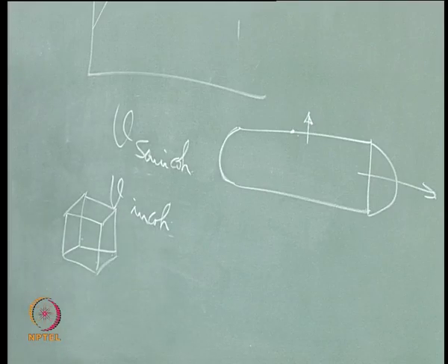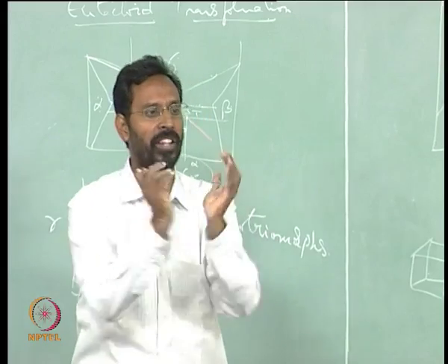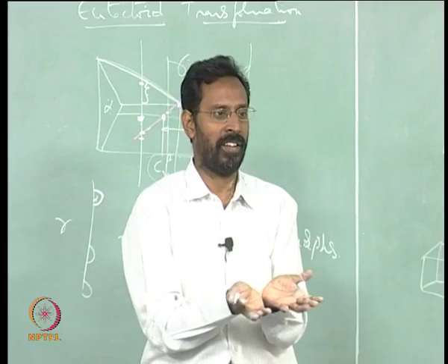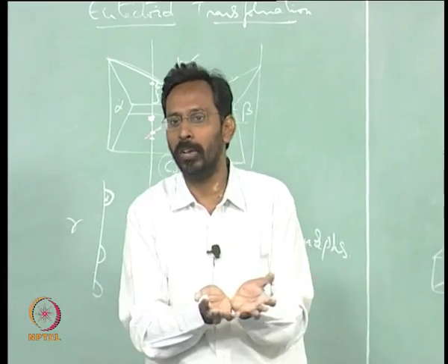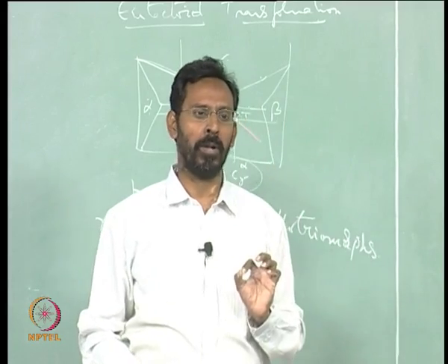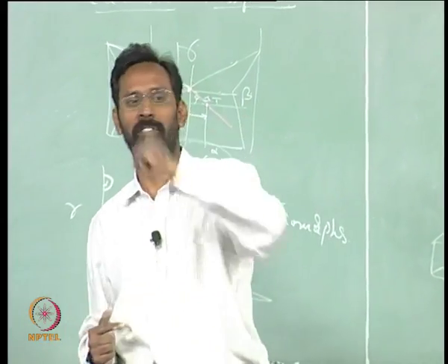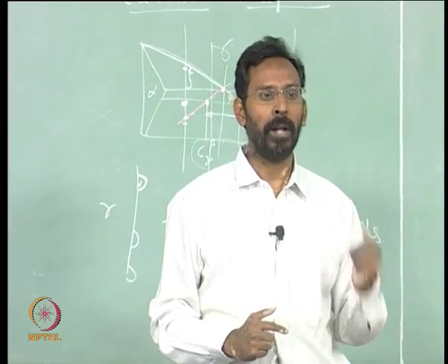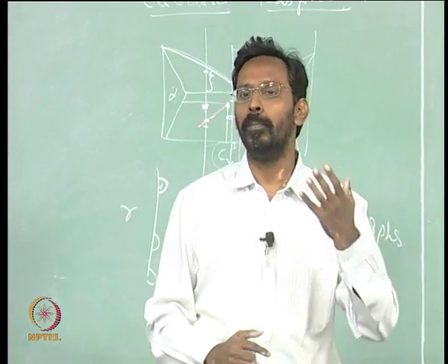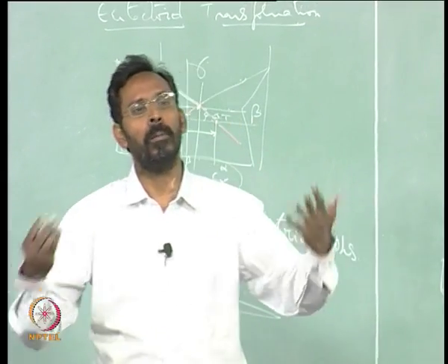Each plane here, if I consider, we have talked about Wulff's plot, that there is a shape for the nucleus. Once I consider there is a shape for the nucleus, there are many planes covering that nucleus. Out of all these planes, whichever plane needs fewer atoms per unit area to grow will be the one which grows faster. That means the loose packed planes will grow faster than the close packed planes. Close packed planes need more atoms.